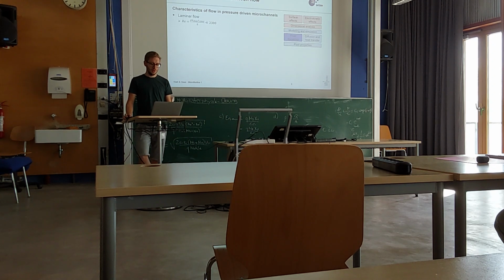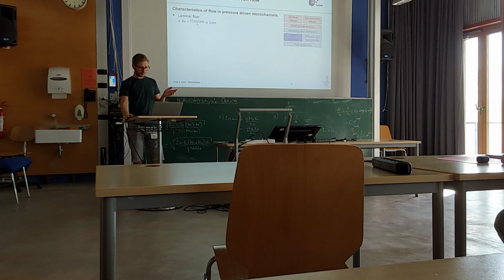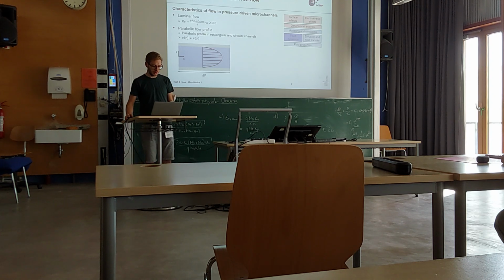I think this could be the case, yes. If we have electroosmotic flow, then it's more or less constant and it drops to the sides. I think I saw, yep, the answer was also in the chat. So in pressure-driven flow, we do have this parabolic profile. So it's not constant, you're also right. Okay, so it drops to 0 at the walls, and then you have this parabolic flow profile, which is